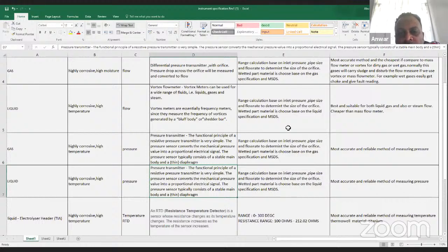Okay, so that is the first criterion. If it is measuring a very crucial parameter that will have an impact either upstream, in this case the storage tank, or downstream of the process, in this case the in-process material that we have, then the selection of the instrumentation will be set for accuracy and also reliability.